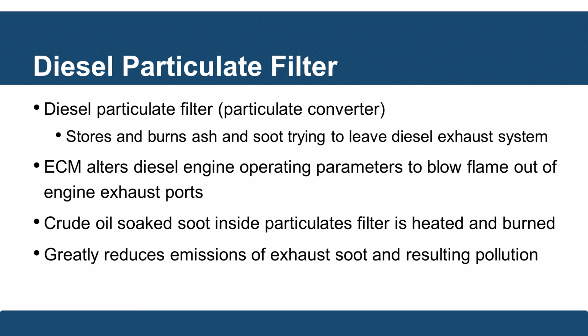All right, lastly, I want to talk about the diesel particulate filter. There's a lot to diesels now. Diesel particulate filters are what they call a particulate converter, and they store and burn ash or soot that is left by diesel fuels because it's not quite as refined. The ECM has to alter the diesel engine operating parameters to actually cause what they call a blow of flame out of the exhaust ports to superheat this burn-off period. This crude oil soaked soot inside these particulate filters is then burned up under that high temperature, and this is what greatly reduces the emissions or the exhaust sooting. This was a major requirement for the commercial industry with these vehicles.